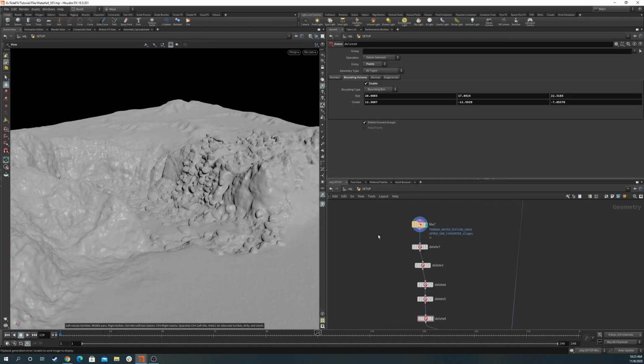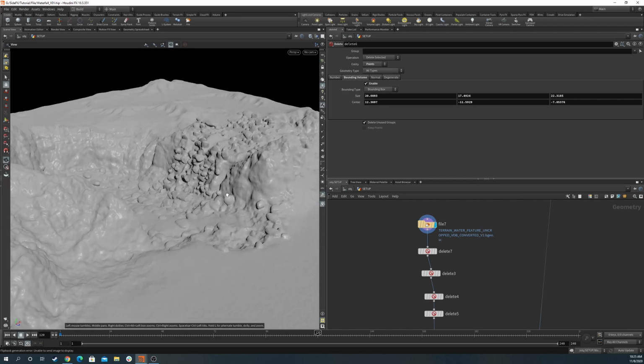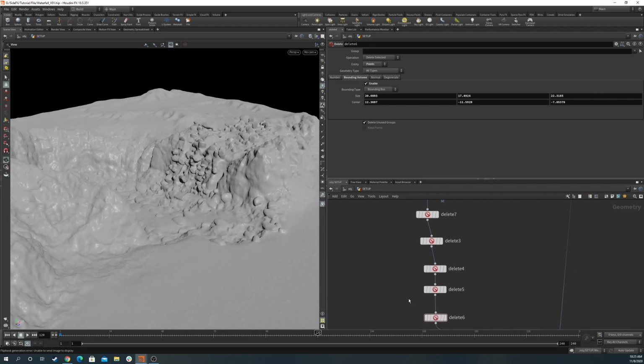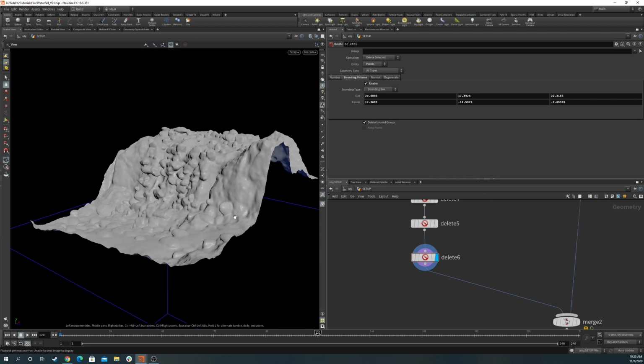This is a quick fix. So I didn't use the old one for the collision geometry. Instead, I used this file. And the process is similar. I use a couple of delete nodes to isolate the part I want to use. And use this one, use an extrude volume to convert to a watertight geometry as our collision geometry.